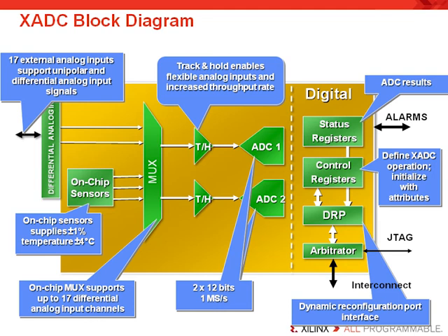Now, the XADC also includes 6 on-chip sensors that support measurement of the on-chip power supply voltage through 5 channels and a die temperature through 1 channel. The on-chip sensors and the external analog inputs are multiplexed and are available to the 2 ADCs. These ADCs may be configured to sample in continuous or event-driven modes.